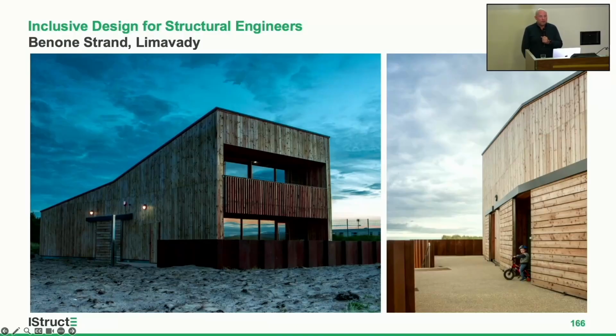It was not inclusive. The wheelchair user, as they went up the ramp, got to the landing, the door that was at the top of the landing, at the edge of the landing, opened outwards, not inwards, because it's windy on the beach and you don't want the doors blowing in. So the wheelchair user would have to pull the door towards them. To do that, they'd have to ease back a little bit down the ramp, which means one hand is holding the wheelchair in place, the other hand is trying to pull the door open. Because it's windy, the self-closer on the door was set at its stiffest setting. So not only is that person trying to open the door while balanced precariously at the top of a ramp, they're having to pull with a lot of force to get that door open.